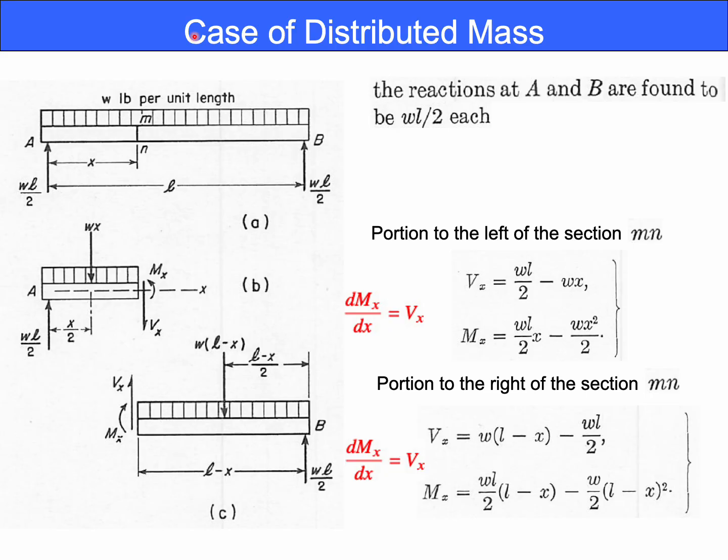Of course, the moment caused by the distributed load is replaced with the concentrated load like this. Okay, please keep this in mind. All right. For considering the balance of the shear force and the moment, we can consider a free body taken from the right side, not from the left side, like this. This will give the same result.